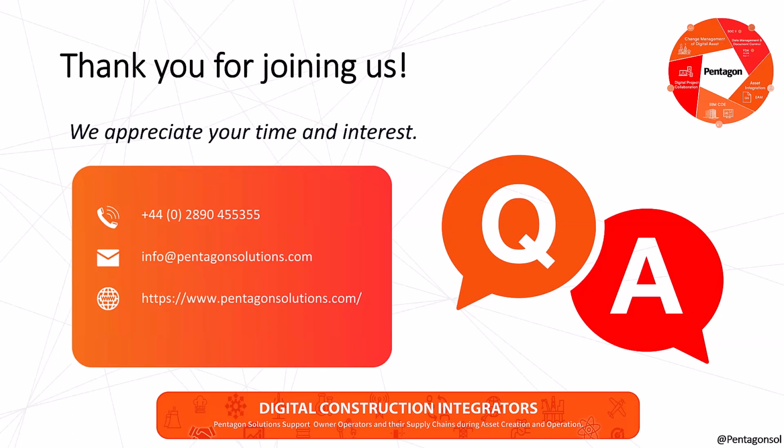Paul writes in, did you use a Revit add-on from AutoCAD to input and export IFCs better into and out of Revit? In this particular scenario, I did, Paul. If you are a Revit user, you're very accustomed to when you start to integrate IFC AutoCAD files into Revit, sometimes all the space information doesn't fully go over, obviously due to the way floors are created and walls are created. However, in this particular scenario, I was able to look at the AutoCAD file itself and use that specific plugin, which allowed a much more streamlined process and full information going across.